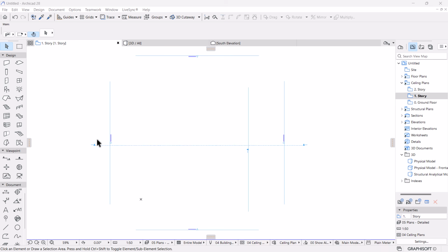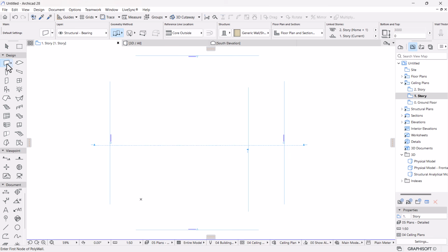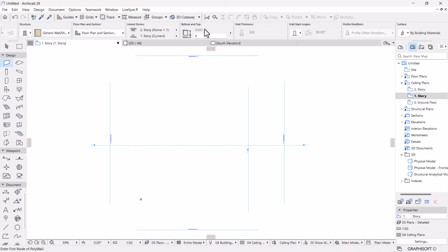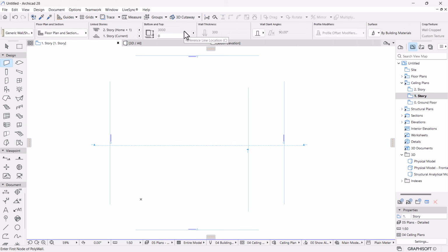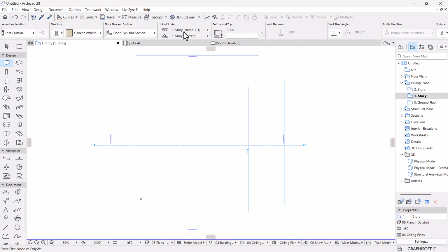So you have your tool settings, and for example, if you click or activate one of the tools here, maybe a wall, under the top section of your interface, it will give you this box. This box has sets of parameters for each element or for each tool you've selected or activated. So currently here we have the parameters of the wall tool.